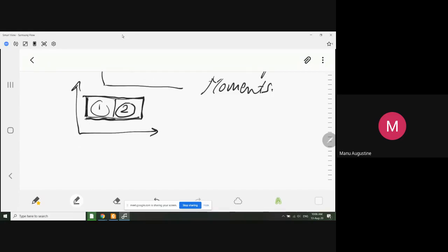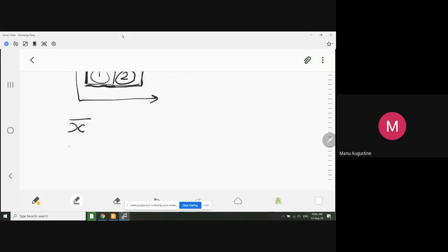So in order to do that, we developed a formula for x bar. Now you have to learn to differentiate between these notations. When I write x1 star or x2 star, that means this is the location of the centroid of individual areas. And when I simply write x bar, this is locating the centroid of the composite area.